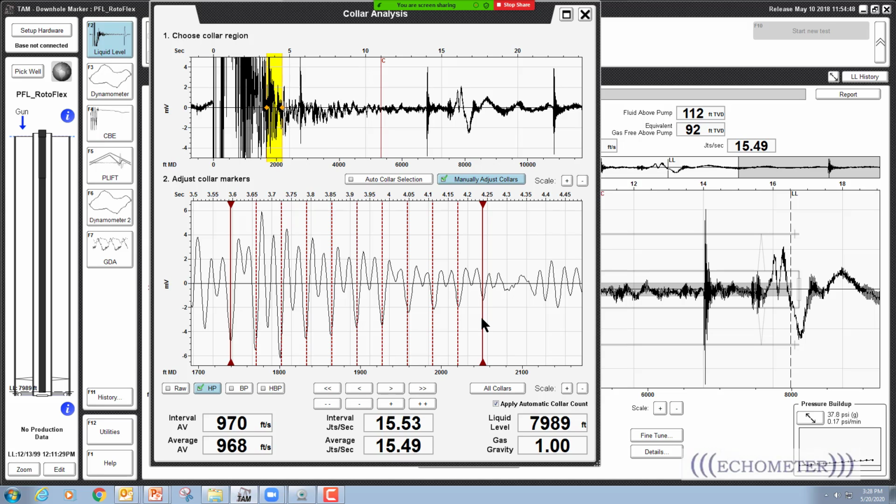So usually you reduce your noise at the beginning of the shot by reducing your differential pressure. So the rule of like 300 to 400 or 500 pounds of pressure still applies when you're doing an implosion shot. You can control the differential pressure by not bleeding all the pressure off inside the gas gun. So the answer is sure, you should control your implosion differential pressure just like you'd control your explosion differential pressure.